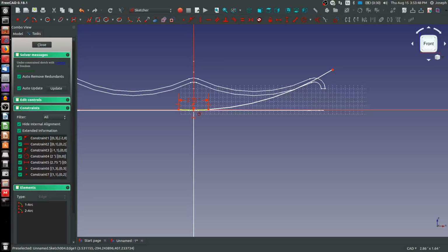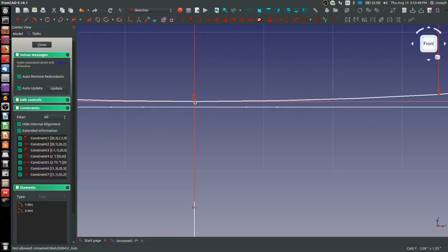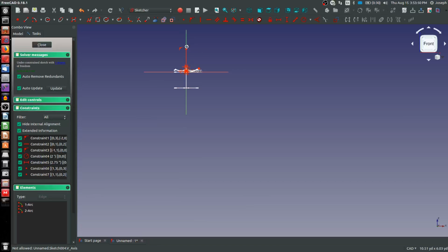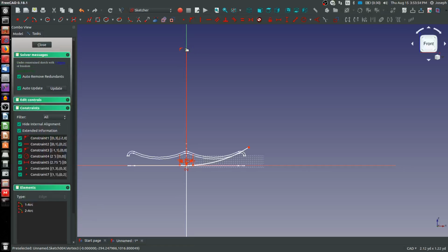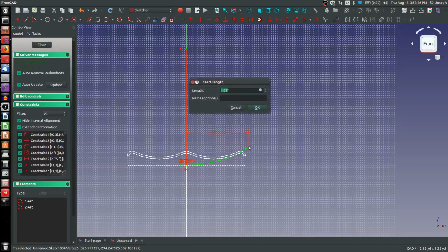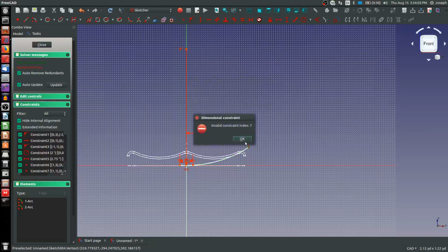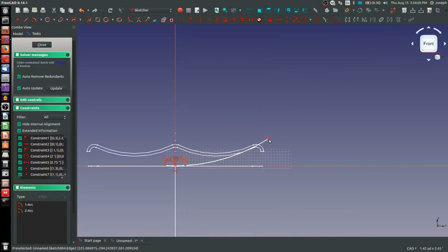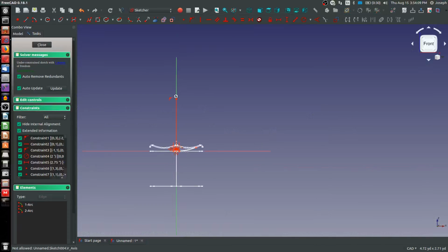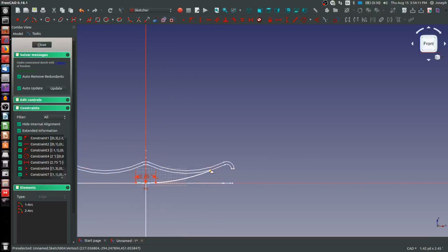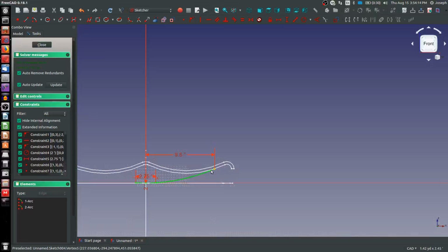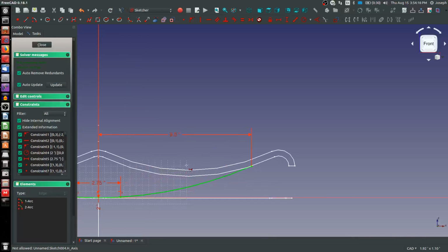And from the center, so I'll take this up, Shift H. We're going to make that 9.5, and not feet, but inches. Of course I've got something invalid, but that shouldn't be invalid. I probably selected the wrong number of things. 9.5 inches, there we go, that worked.